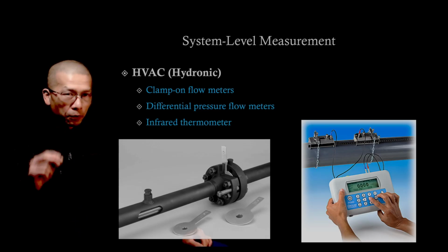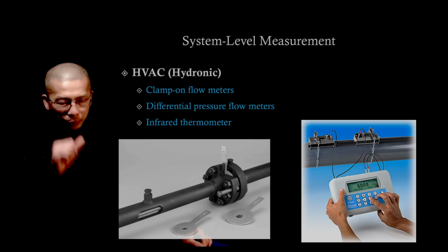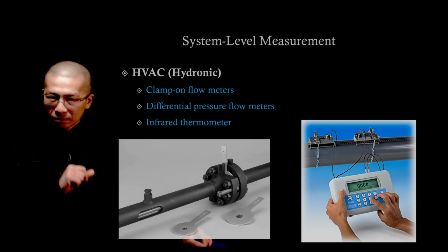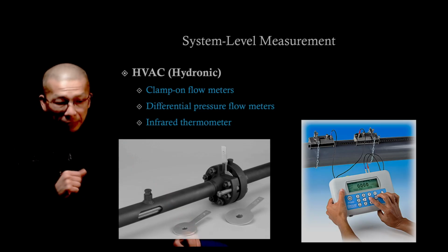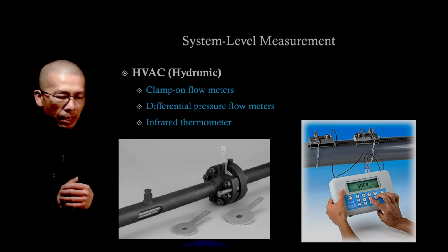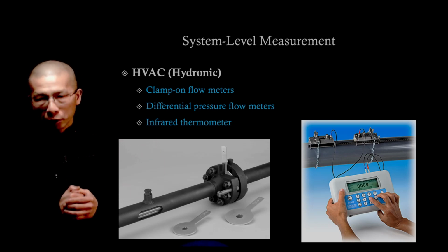The new pressure difference is proportional to the new flow rate divided by the old flow rate, squared. So anyway, we do not want to have too high a flow rate. It really wastes a lot of energy.